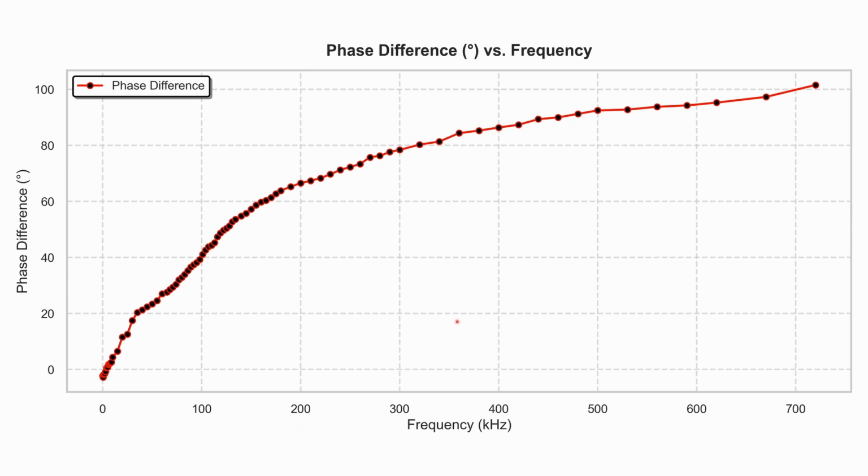the input. As the frequency increases, the phase difference grows, with a rapid rise between 0 to 100 kHz and a steadier increase beyond 200 kHz. At a higher frequency, the phase difference approaches 100 degrees, indicating a significant lag. This behavior aligns with the low-pass filter response.